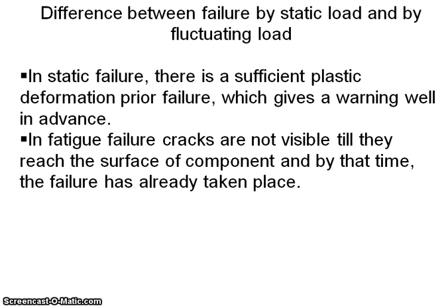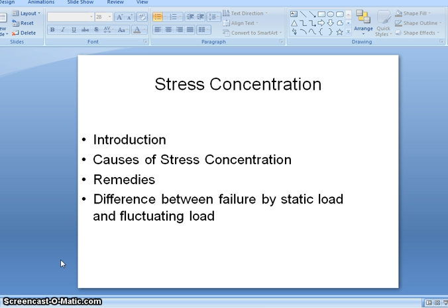So in general, when a component is subjected to the static load, it will give us a warning well in advance. While in case of a fatigue failure, the cracks develop near the discontinuity of a component and are not visible to us, and when they reach the surface of the component, by that time the failure has already taken place. So this is the difference between the static load and the fluctuating load.